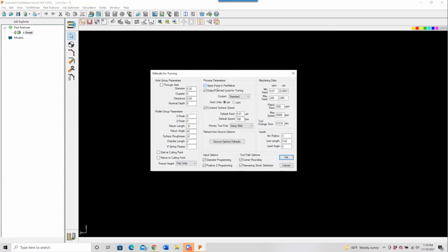If I have a tight tolerance, then I will apply comp in PartMaker as a global value to get the code into the general area for the diameter values I'm looking for. And then what I'll do is I'll go into the process table and I will add compensation into the toolpath for wear compensation. So PartMaker outputs the comp code for you, and then you can adjust that code at the machine with your wear compensation page, okay, if you need to sneak up on a tight tolerance.